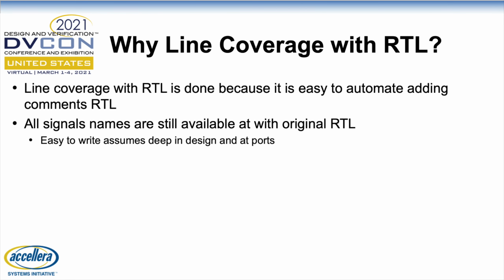One of the main ideas behind this approach is we want it to be something that's automatable. We don't want a lot of human interaction. And so to make it easier, we want to do line coverage with the RTL. Some of the benefits are it's easy to comment lines with a script. You don't have to rewrite RTL or do anything fancy. And signal names are still available with the original RTL. For example, all the design ports and even internal port names are still accessible with the assumed statements that you might be writing to constrain your stimulus in a certain way.